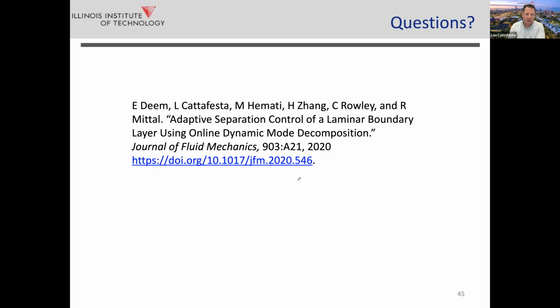Yeah, I think that's very much the point. Remember I showed you with actuator location relative to the separation bubble, the so-called optimal frequency changes, the length scale is changing, so the size of the bubble is changing, so the optimal frequency changes. And this approach doesn't predispose you to determining what the shear layer frequency is or what the bubble frequency is.